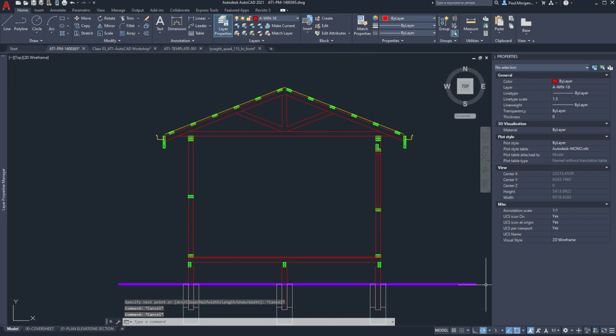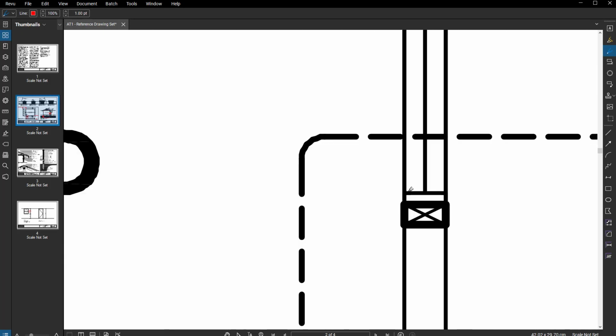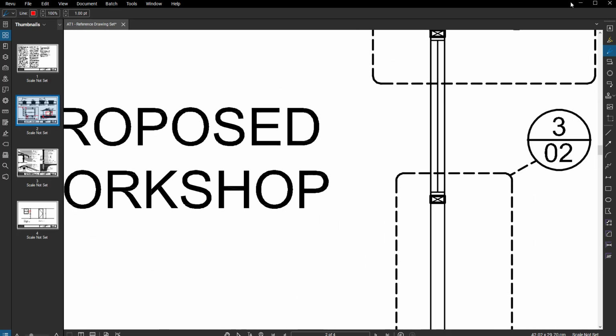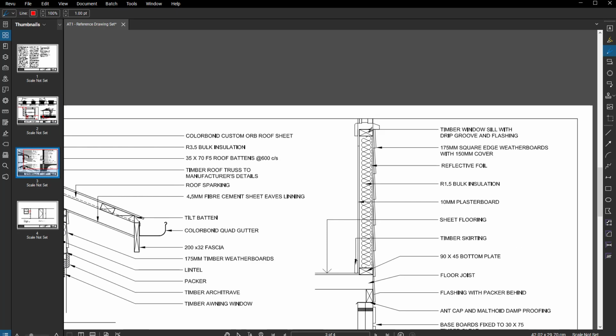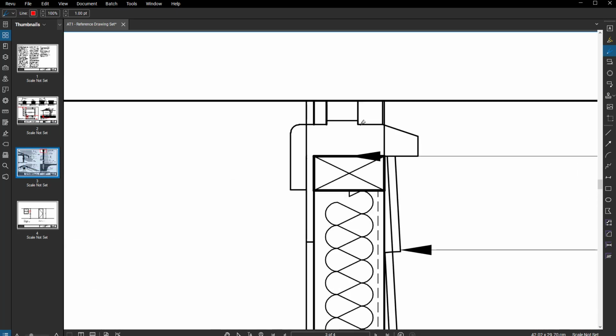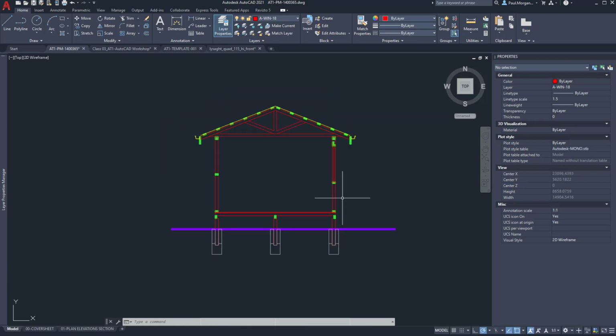Now I want to double check that's how it was done. Yeah, looks good. In fact, here the windowsill is less than 50 mil, so we might do the same thing. Especially when we look at the detail. If we go to the details, we can see what that looks like. So you can see that you definitely detail this up a lot more in terms of what this windowsill looks like. Though I think the 50 mil is probably appropriate. So I'm going to leave ours at 50 mil. And that's our geometry done for our section.